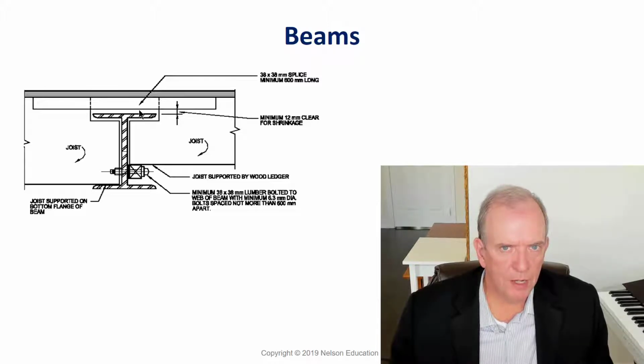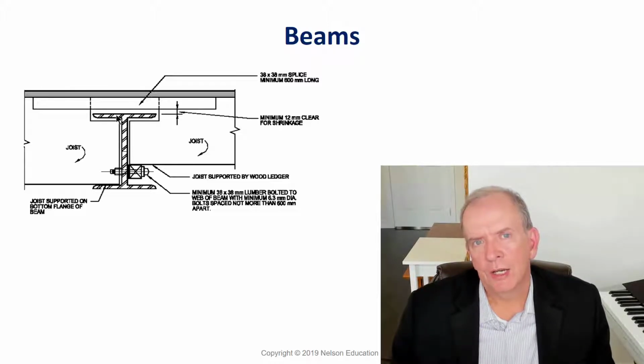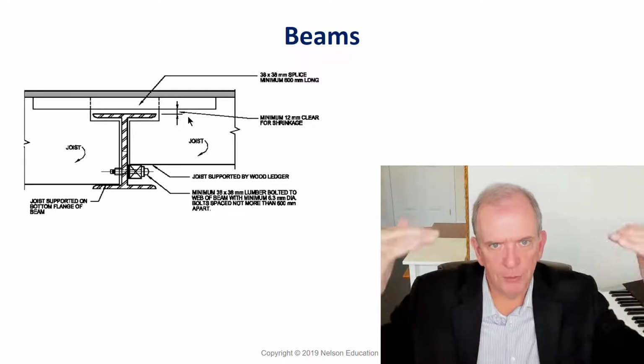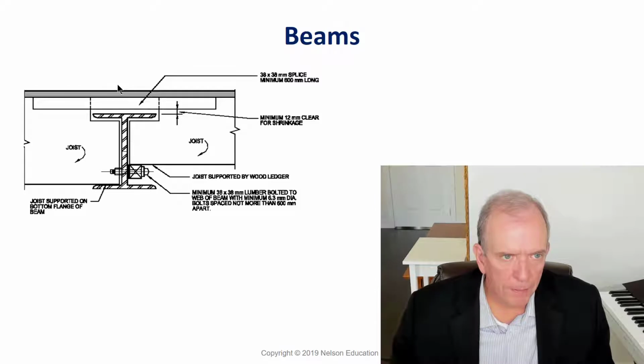Well, we spent a fair bit of time in lecture 3A talking about shrinkage. Some conscientious carpenters will cut the piece and make it fit exactly there so it's really strong, thinking, I'm doing a great job. They just caused a problem, because when this lumber joist shrinks and this lumber joist shrinks, if this was tight here, what's going to happen when that pulls down? It's going to leave a hump in the floor.